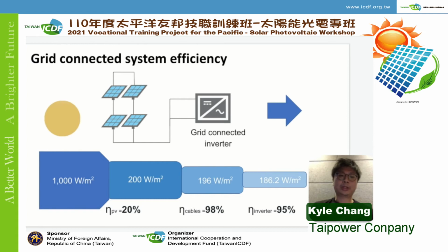And then the balance of the system could be placed at a considerable distance from the PV array to protect the inverter against the weather conditions. In this case, this loss may be important. Depending on the length of the cable and the current, this loss can be around 1 to 2%.